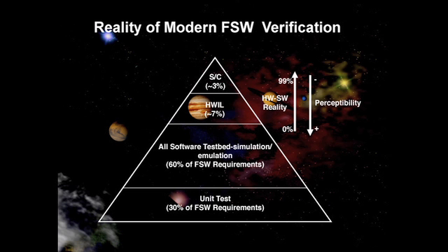You might have enough money in an infinite budget to make a hardware-in-the-loop do it, but you'll never have enough time at the spacecraft, and you'll never be able to inject all the faults you need to, or put the fly wires on the vehicle in order to give you that observability. So Test Like You Fly has a huge problem now, and you better make sure that you certify these test beds, because you're buying most of the mission off with it.